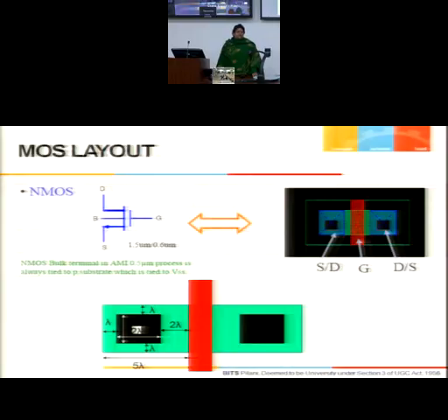So one way is that you do not fabricate a very large width, because large width means the total area is going to be very large, 80 lambda square. Here I have taken an example of a width of 80 lambda. Rather, you work with smaller width. But with a smaller width, I cannot get the current drive. So what is the way out?